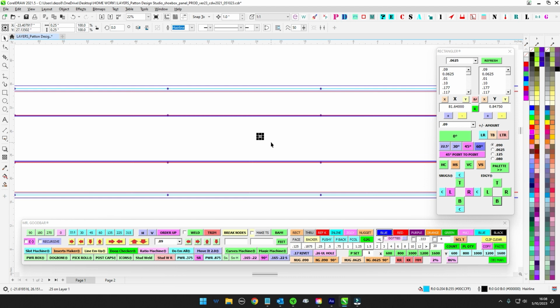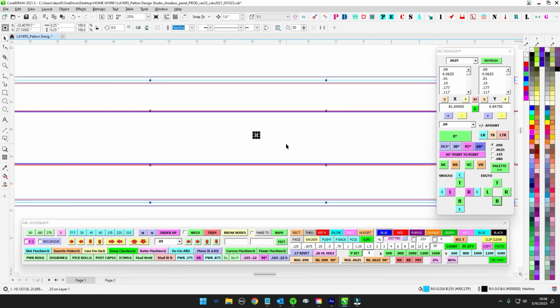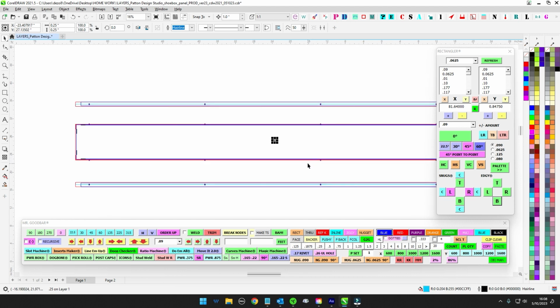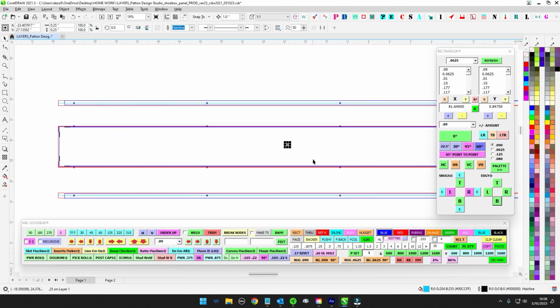They might be using drywall screws or gold screws into studs. Those are 3/16, so a 1/4 inch hole is good for that. You can always drill a hole out. If it's a little too small, the installer can just grab one of their drill bits. It's a little pain in the butt, but they got it. It's fine. What you can't do, other than putting washers onto a screw, is make it smaller. You don't want too much slop, obviously.